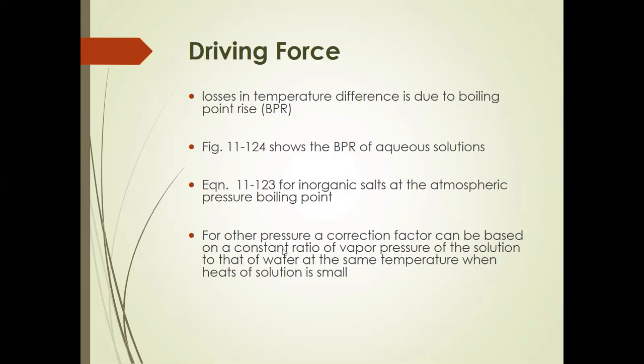Now, for other pressures, since we are only limited to atmospheric condition for both figure 11-124 and equation 11-123 in your handbook, there is a corresponding correction factor for that. That particular correction factor should be made known or should be specified in the problem so that you can apply such correction factor in terms of the correct boiling point of your solution later on.